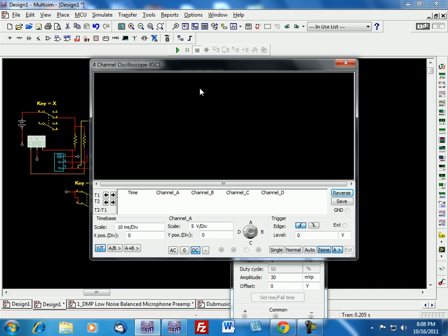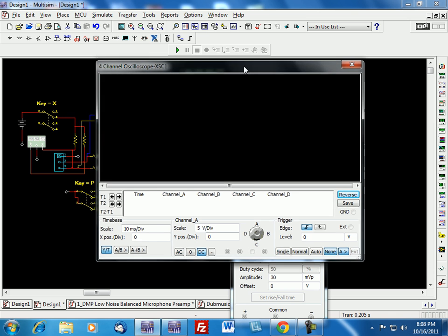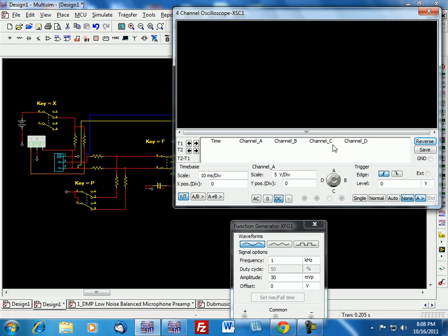And again, this is if I was in the real world. Before I turn it on, let me set the scale of the oscilloscope. I'm going to use 1 volt scale AC for both the A and B scale. Well, no, let's go down to 50 millivolts for the A and the B scale. 50 millivolts A and B scale, and the D scale, we're going to set at 1 volt.